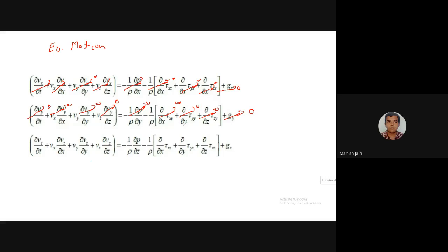In third equation, on the right hand side, you have Vz, but Vz will not depend upon time. Vx is zero, Vy is zero, second, third term. Fourth term, Vz will not depend upon z. Vz is only depending upon x-axis. So all these terms are zero. Here pressure difference is not there. It is freely falling, not due to the pressure.